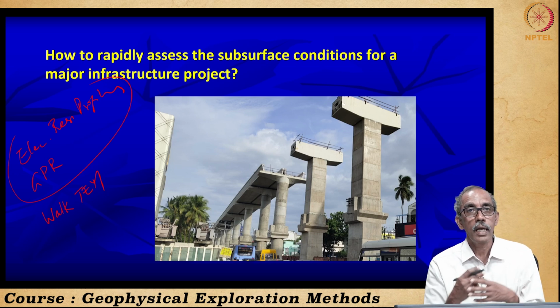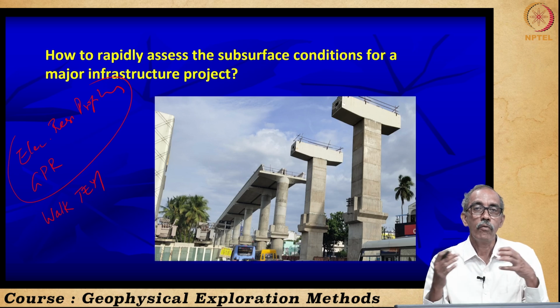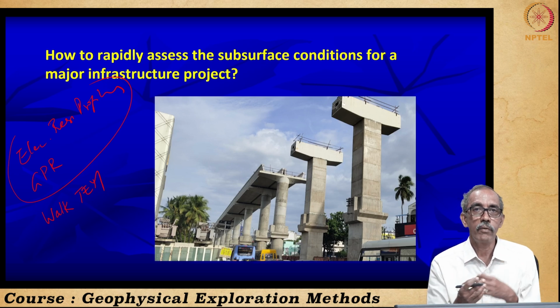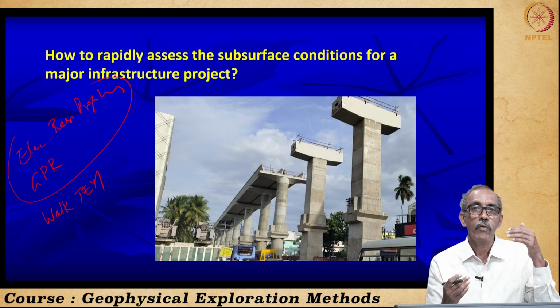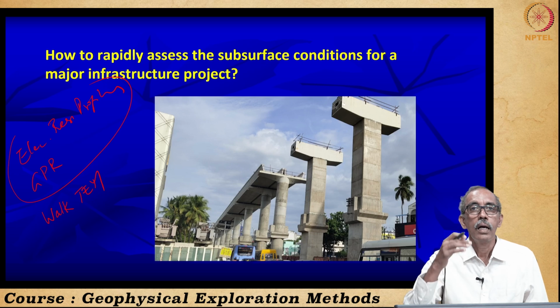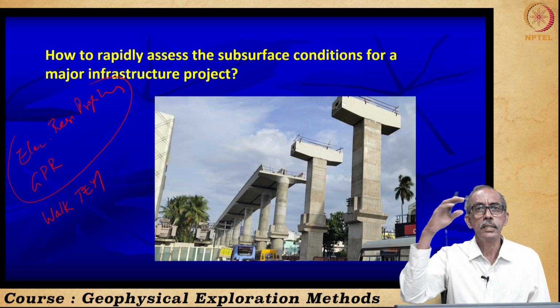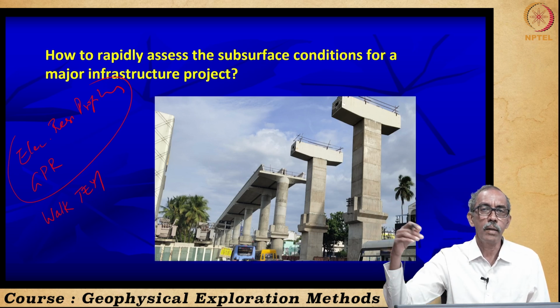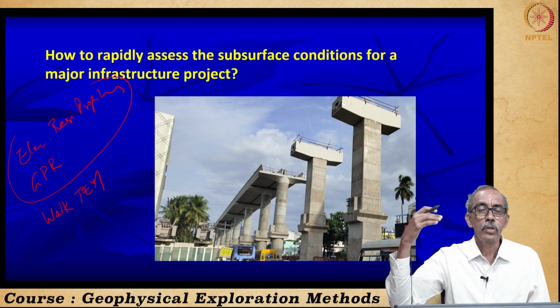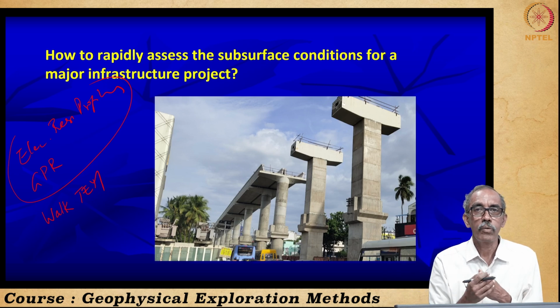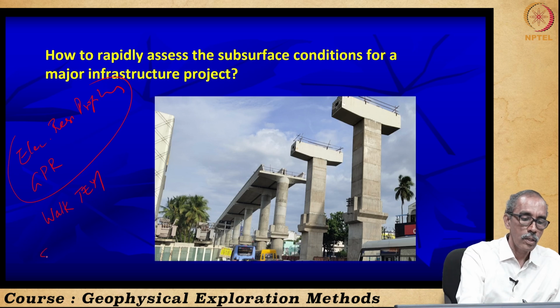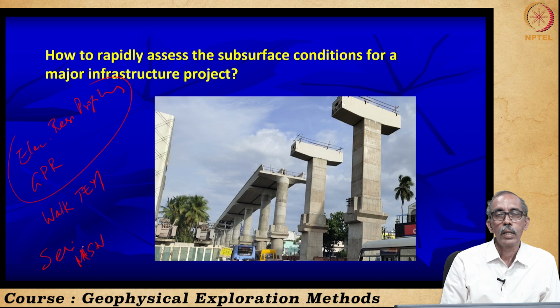To understand the climate change impacts on water balance of the earth, we can use gravity methods. For a geotechnical purpose, to identify a suitable site for laying foundation for a major infrastructure project, a major dam or a nuclear power plant, to understand the foundation strata characteristics, we can use seismic as well as multi-channel analysis of surface waves, MASW.